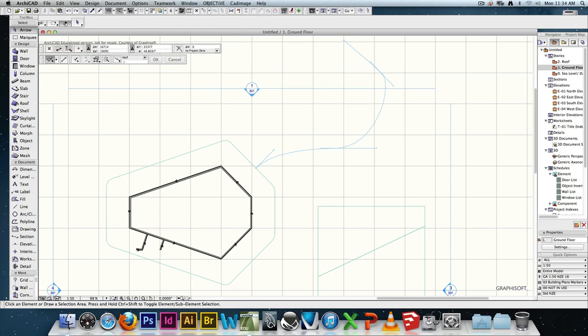But a path is a little bit more complicated than this big wobbly spline that I've got. So I need something to help me. What I need is another line offset from that line. Yeah, but see the slab, I've got to define the inside edge of this, right? Because that would have to be along here. And I need to define that side as well, which doesn't exist at the moment. So what I need to do is offset this edge.